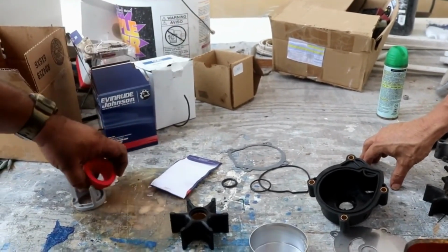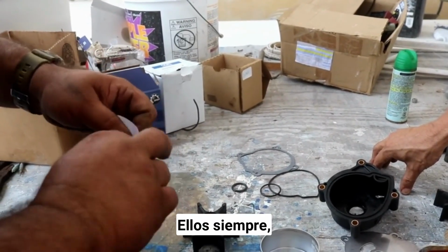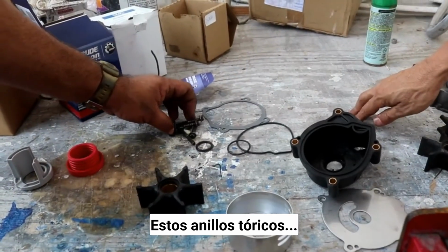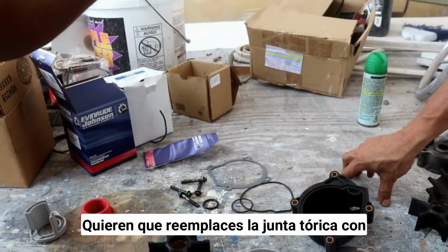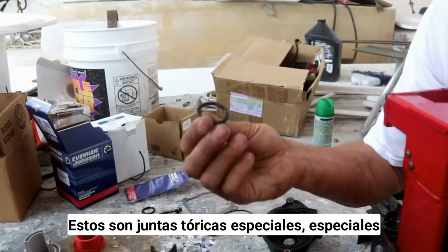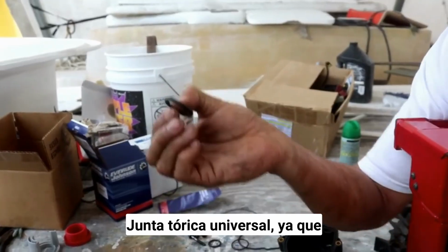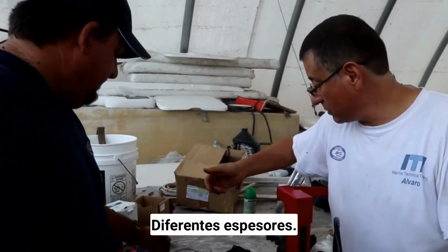Then you also have the screws. You never want to reuse the same screws. Never. Now these O-rings are for the actual water tube that comes from the power head. The manufacturer wants you to change the O-rings. Those are special O-rings, a special material, a special color. Don't try to replace them with generic O-rings, because it's a different material and different thickness.